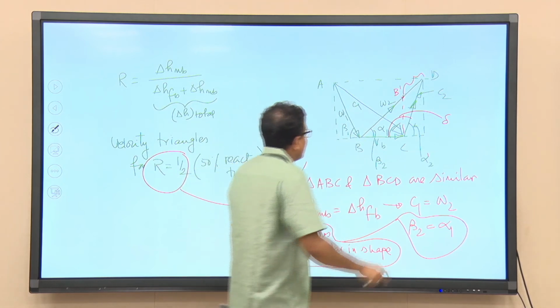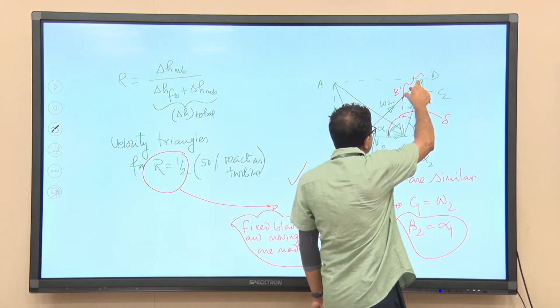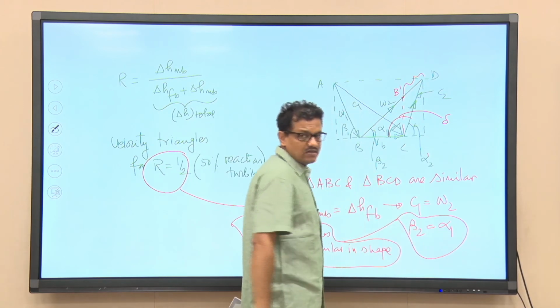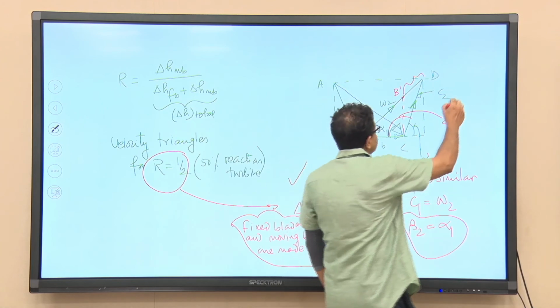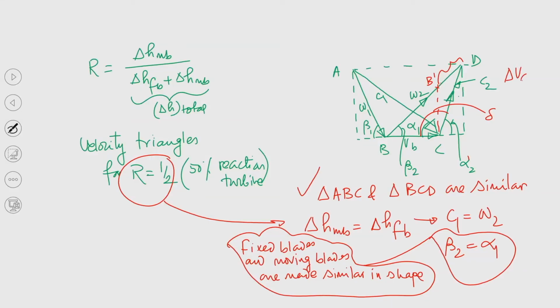But here we are having this additional magnitude of this velocity, as a result of which you can see delta V A, or rather delta C A I will be writing, delta C A equal to 0. So, there is no axial thrust to be precise. So, delta C A equal to 0. So, it implies no axial thrust.